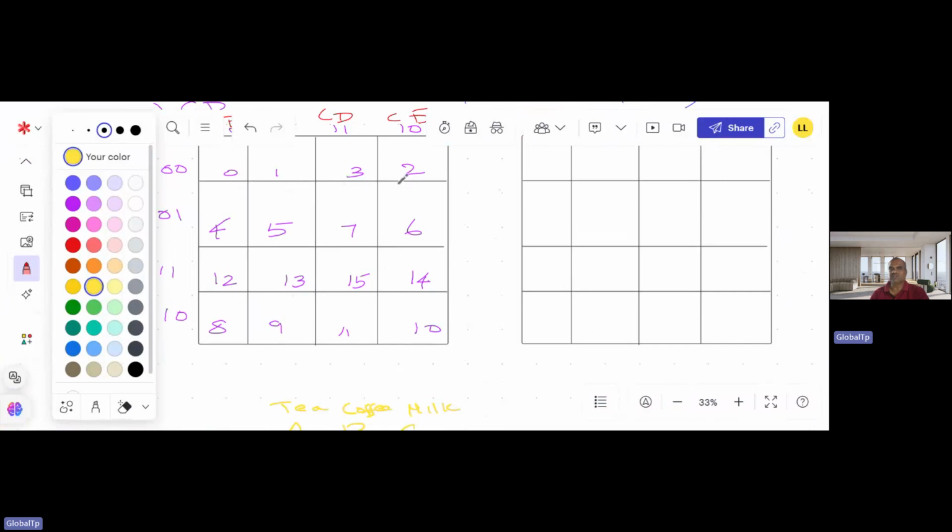Everyone is thinking that is a hard and fast rule. But that is actually not a rule. Here we are writing 0, 1, 2, 3 only, but 2 is represented as 3 in the form of gray coding. We are following the gray coding technique here. Why we are following gray code, the elaborate answer is available one step behind. Already a basic K-map video is uploaded. You can go and watch there. More information will be available.